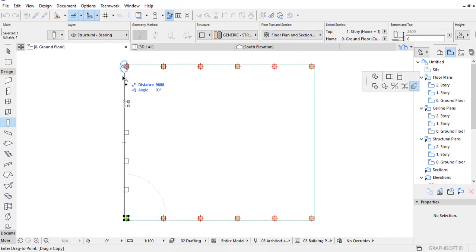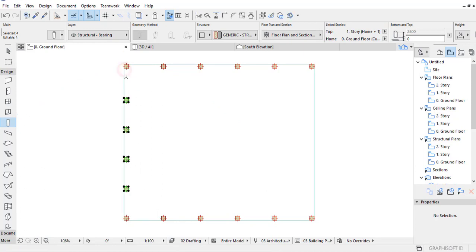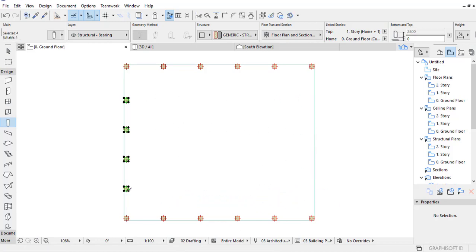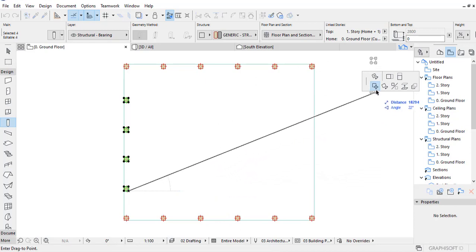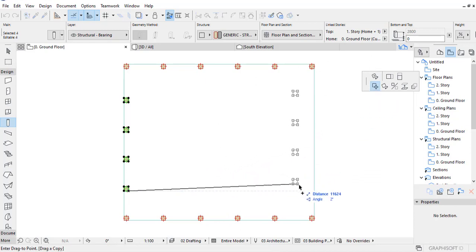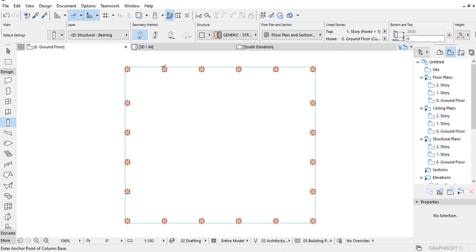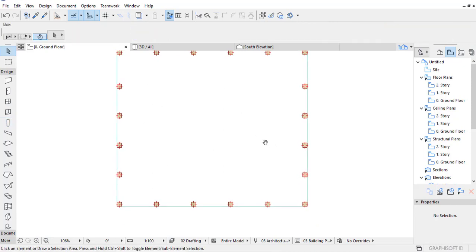So this is going to create 1 copy less. So 5 minus 1, 4 copies. And then you can activate Ctrl D as the shortcut. Click on this point and tap on Control. I should have selected this point instead. Start dragging it, tap on Control, click onto this. So likewise you can make copies in the center as well.